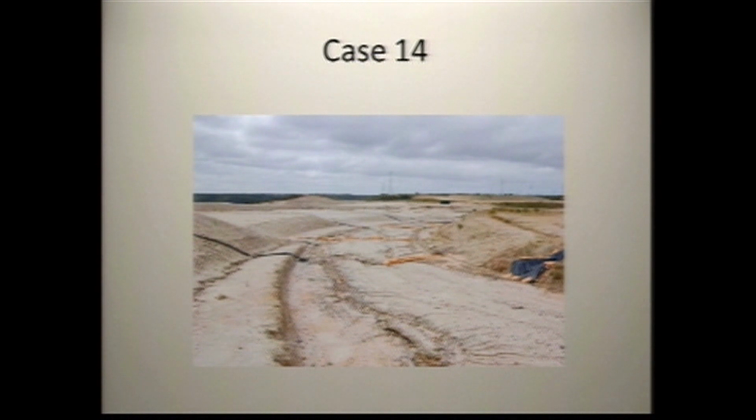Looks like until it's sloped there, it looks like some sediment control. You need chevrons or something to stop it. Oh, you can see them at the bottom of the picture. Looks like gravel bags. Yeah, so they have some, but there's not enough, right? What was the fundamental rule that we just talked about? If you got rilling in between the bags, there ain't enough of them.